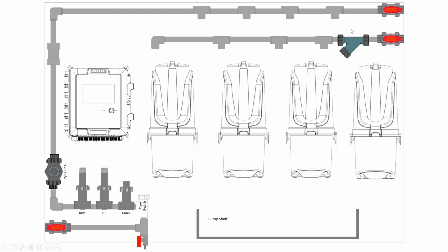We also always put some sort of a mesh strainer on there. The UltraM has a little tiny screen in it, and if you clog or foul that screen, you will have lessened your performance, and it's a little bit of a bear to rebuild. So by having some sort of mesh or strainer ahead of it that you flush on a regular basis, you're going to reduce that maintenance issue.